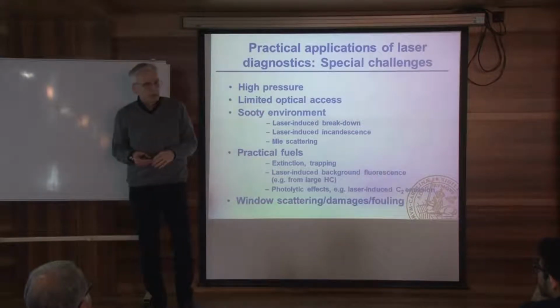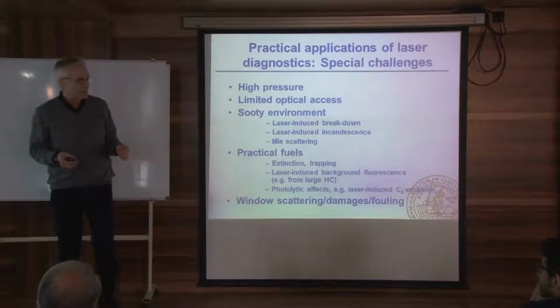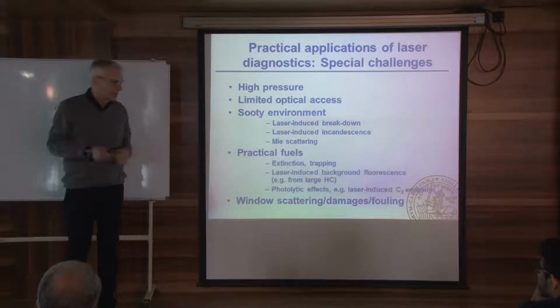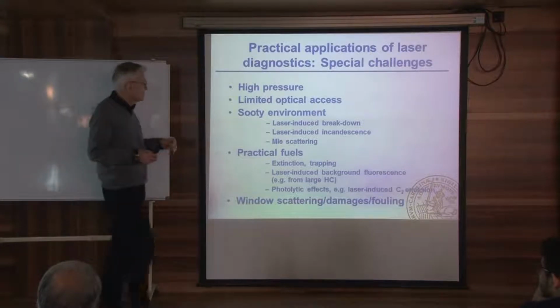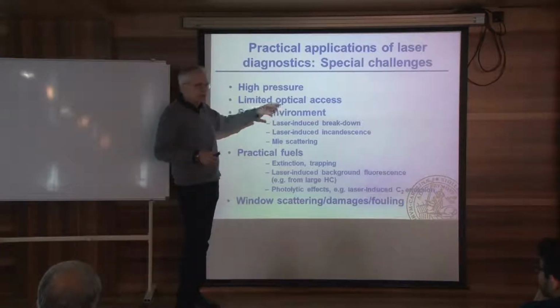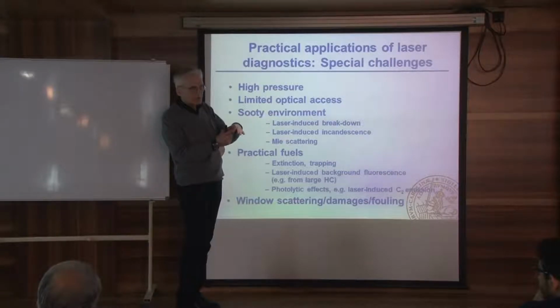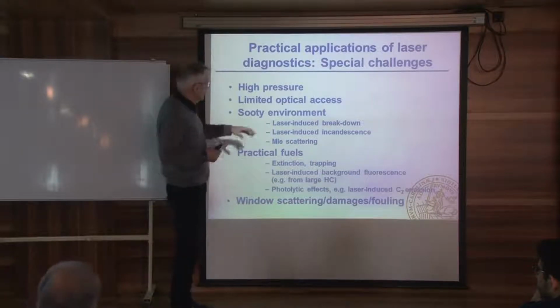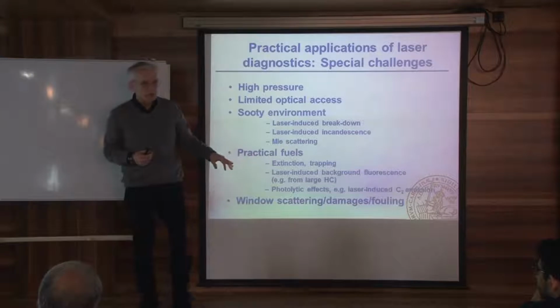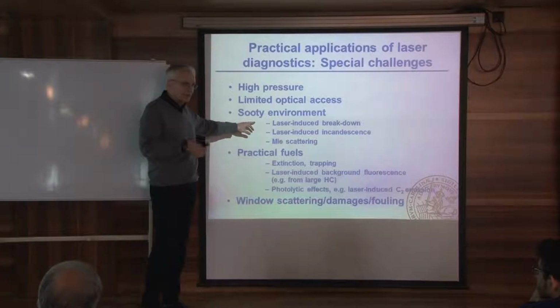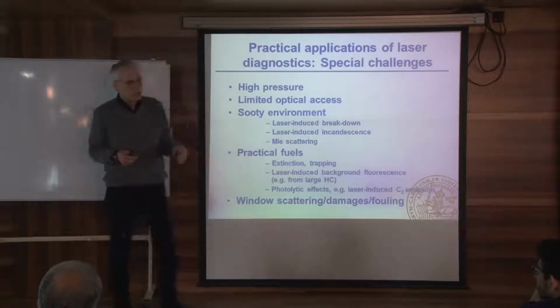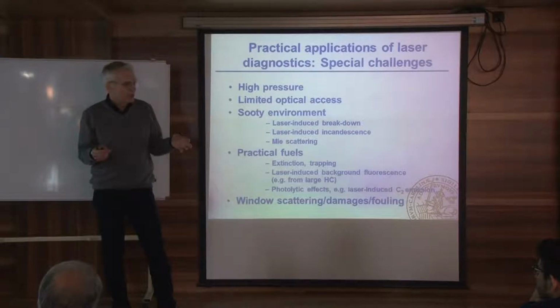We might run into problems with limited optical access. If we want to do experiments in a big fire experiment, in a boiler, engines, gas turbines, we have to have optical access. We have to put a window into this device. And that might not always be easy. We many times have a sooty environment. If we want to study soot, of course, then it's straightforward. But if we want to measure concentration of NO in a sooty environment,